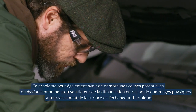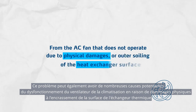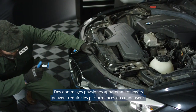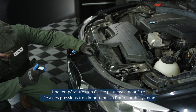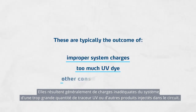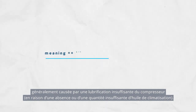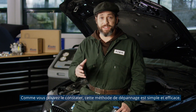This can also have many potential root causes, from the AC fan that does not operate due to physical damages or outer soiling of the heat exchanger surface. Corroded and missing fins are typical for climates with a lot of moisture and where salt is spread during the winter. Seemingly light physical damages can reduce operation of the condenser. Too high of a temperature is also related to too high of a pressure in the system. These are typically an outcome of improper system charges, too much UV dye, or other consumables in the loop. High temperature can also relate to overheating, and this would normally mean not enough lubrication of the compressor, meaning there was no oil or improper oil was applied. As you can see, this troubleshooting method is easy and effective.